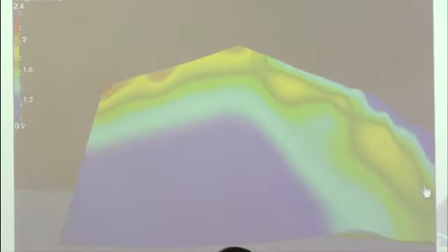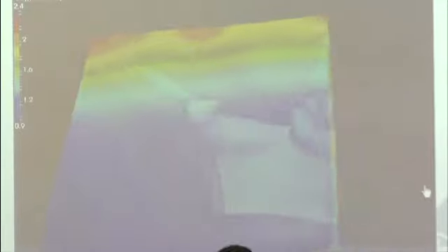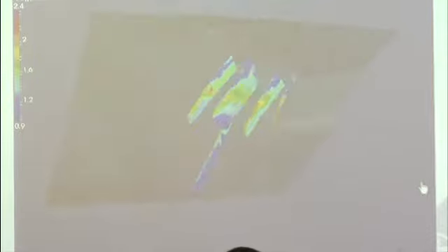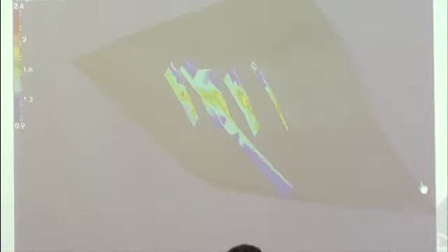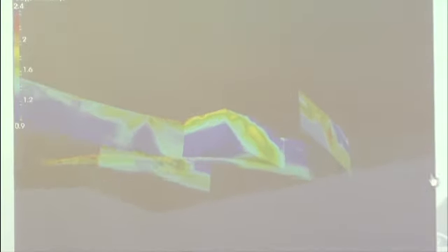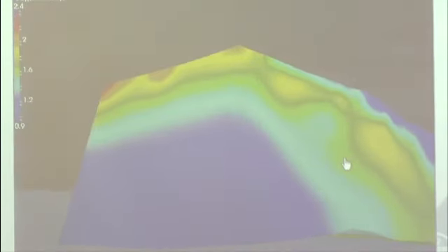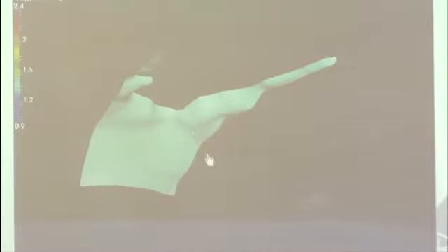They're all on the same colour scale, so the blue colours are low resistivities. These are associated with mudstone formations at the site. The warmer colours, the greens through to the reds, they're higher resistivities. They're associated with a sandstone formation. And the upper mudstone layer is less competent than the sandstone, and it's slipping down the hill. The area we chose to install the permanent arrays actually covers 2 of the active lobes of the landslide. You can see them clearly in this ISO surface here. These are the edges of the lobes where the mudstone has slid over the top of the sandstone.